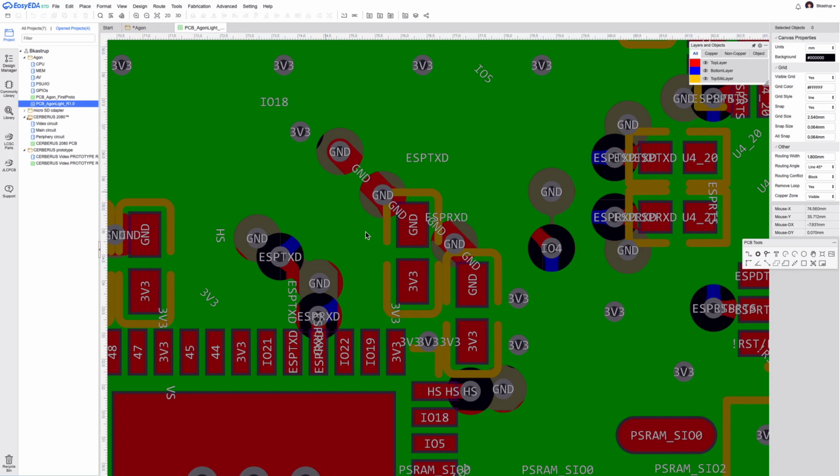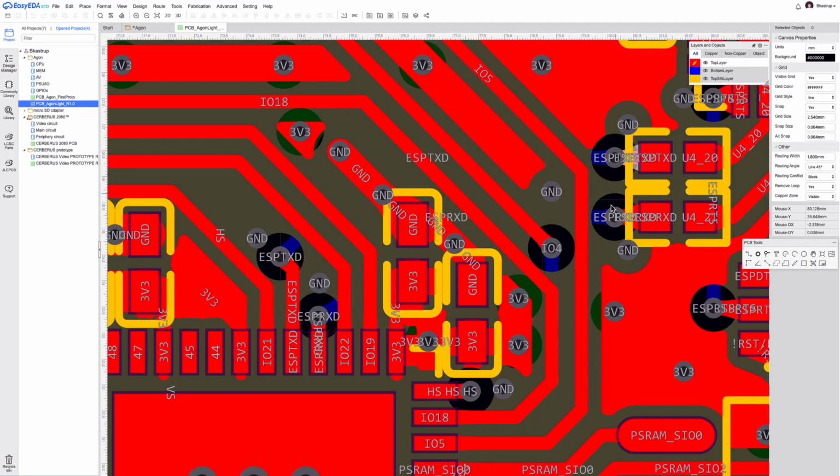And when you have this change of reference plane, to keep the field compact, preventing it from spreading around, you need a via, ground or VCC, right next to the signal, so the electromagnetic field fringes, when they go vertical and down the board, couple vertically to the via next to it. Now I'm always using ground vias because these are also return path vias, not only reference vias.